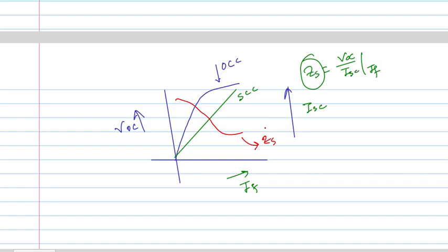Now the question is, throughout this test you will find a lot of Zs values. Which Zs should I take for further calculation? Remember always, the machine is designed to operate almost in the magnetically saturated area. That means the machine is operated in this zone. So we take the possible minimum value of Zs from the experiment.